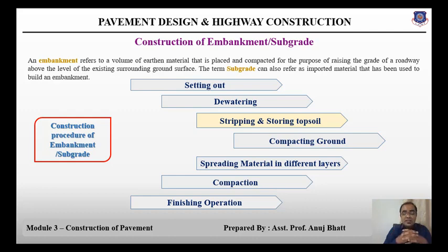When so directed by the engineer, the topsoil from all areas of cutting and from all areas to be covered by embankment foundation shall be stripped to a specified depth that should not exceed 50 mm, and stored in stockpiles of height not exceeding 2 meter for covering the embankment slopes, outslopes and other disturbed areas where revegetation is desired.